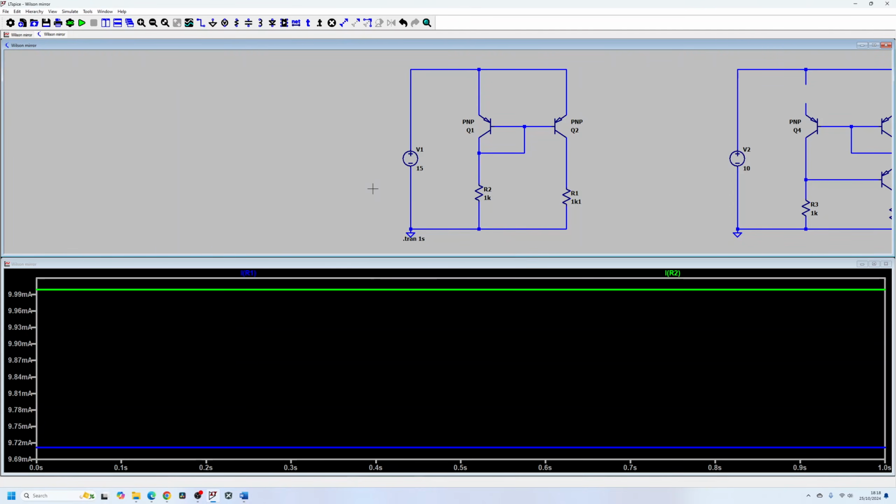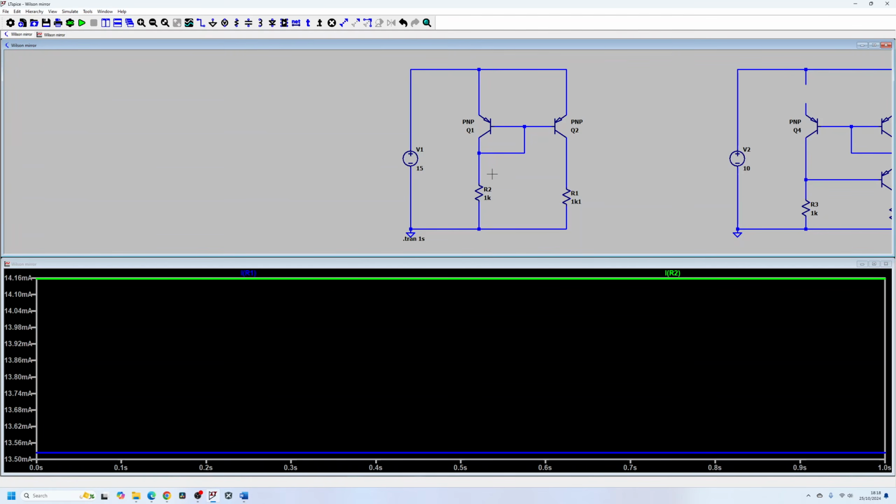But one of the things hopefully you notice now is that we have changed our programming current. The programming current is directly dependent on our power supply. So we have 15 volts over here now. We're going to have a 0.8 volt drop on this junction because of this transistor's base emitter voltage, so we're going to have approximately 14.2 volts on this junction. That gives us 14.2 milliamps flowing through this resistor. So obviously you can see that it's no longer the 10 milliamps that we previously set. If your power supply varies, basically this circuit is not that useful.